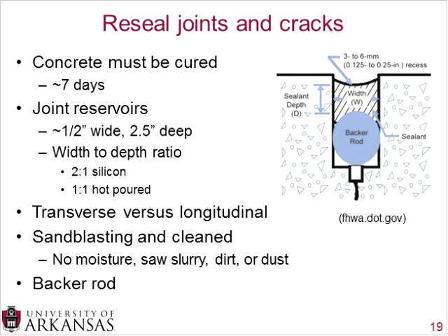So talking about the construction of these, when you're resealing joints and cracks, it's very important that you make sure the concrete is at least partially cured, and approximately 7 days is a good rule of thumb for this. You don't want to make one of these joints or reservoirs with concrete that is either not cured enough or, on the other hand, cured too much. If you wait too long, other cracks can form, or it becomes very hard, which can cause additional damage when you put that saw in there. So you want to look for about a 7-day cure time.